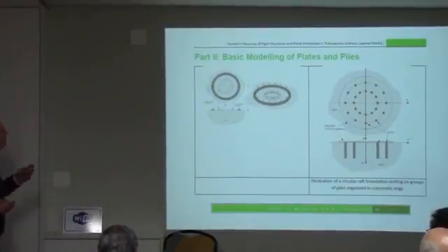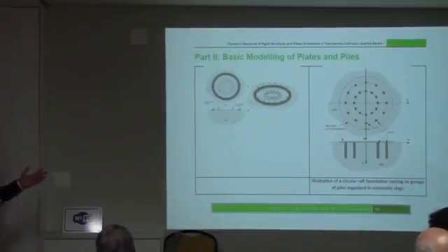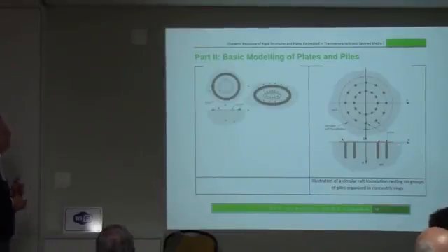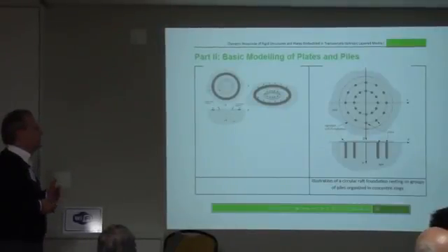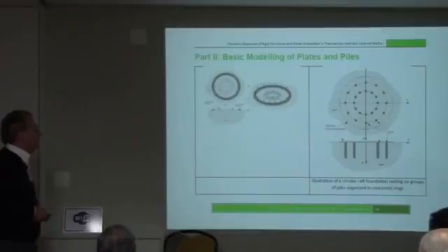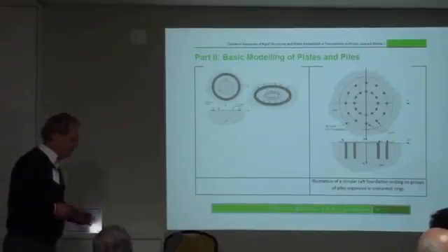So now when it comes to the issue of modeling, there are some issues about what we're going to try to model: a flexible foundation resting on a group of piles. A lot of work has already been done on this. But there are some challenges to be able to model this with a huge number of piles, up to 500 piles. And we're starting with an axisymmetric model, as we will see. As we move on, the improvement will have to go to 3D analysis, but this will be work to be done in the future.